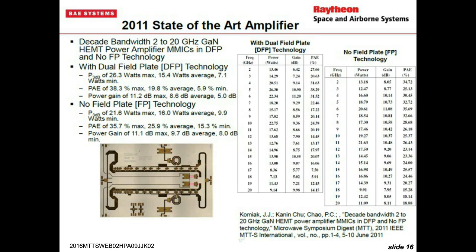This is a non-uniform distributed power amplifier, 2 strings. If you look at each string, you'll see 2 things about it. Number one, you get clumping of the devices on the left, and that provides non-uniform periphery. The optimum impedance for those first devices is on the order of several hundred ohms. You can't realize that in microstrip.